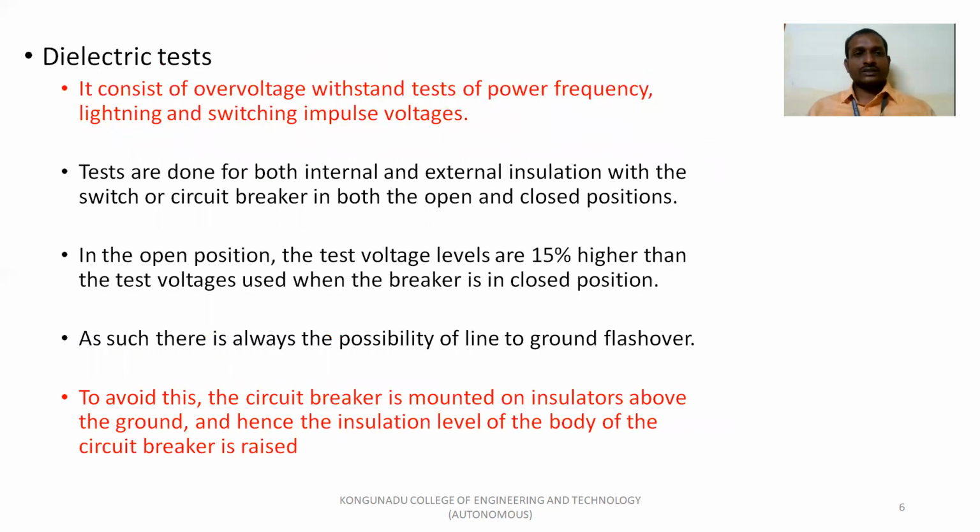So first we are going to discuss the dielectric test. It consists of over voltage withstand tests of power frequency, lightning, and switching impulse voltages. So three different voltages we are going to apply to the equipment, and we are going to verify whether our equipment is capable of withstanding these voltages or not. One is power frequency over voltage, another is lightning over voltage, and another is switching impulse voltage.